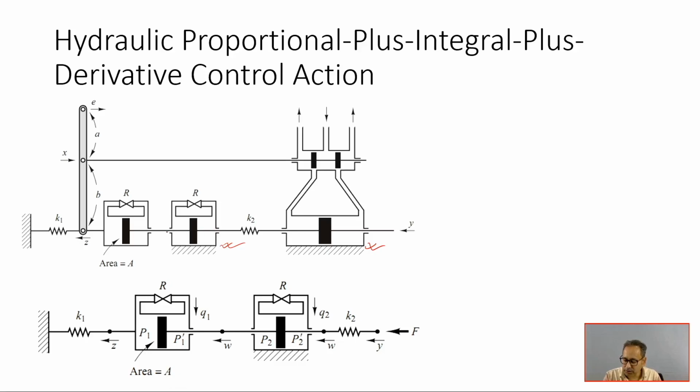Here these two dashpots are of different design. One is through spool, and in the other the spool is connected at one end, the other end is not connected. That is shown separately in this particular figure. Here y is the displacement coming to this side of the power piston, and that is affected here also, because this is the through spool. So y will be here also, but the displacement at this point will be different than y because of the existence of this compliant element K2.